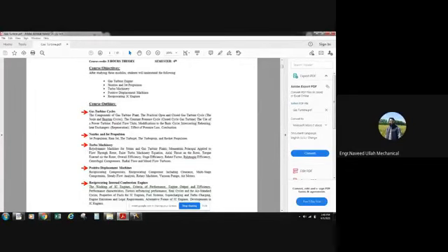Right, and then after that we have actually two topics. Those are, you can say, they are actually the mirror image of each other. One is the turbo machine and the other one is the positive displacement machine. In positive displacement machine that we will be discussing in chapter 12, what happens is that a specific amount or a specific volume of the working fluid is taken in, and a positive work is done on that volume, and it is delivered at elevated energy or elevated pressure.